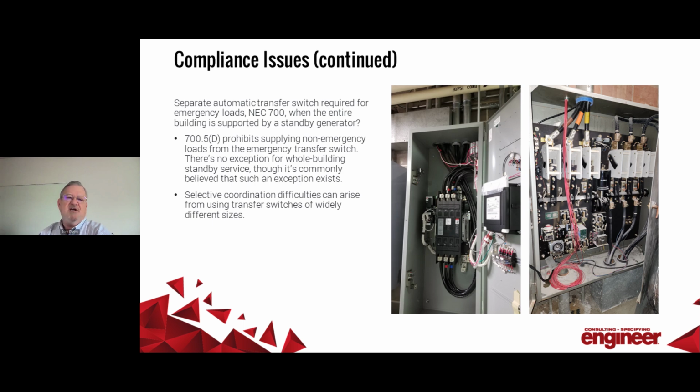Another question: is a separate transfer switch required for Article 700 loads when an entire facility is on standby power? And the answer is yes, it is required. The NEC says that a transfer switch that serves any emergency loads cannot serve any other types of loads. There is no exception for a building that's completely supported by standby service. You might be surprised how many people feel that they can use a single transfer switch to power an entire building and that it will serve both emergency and all the other loads. That is not the case.